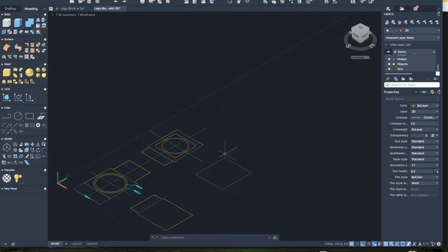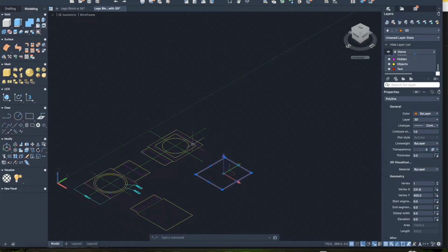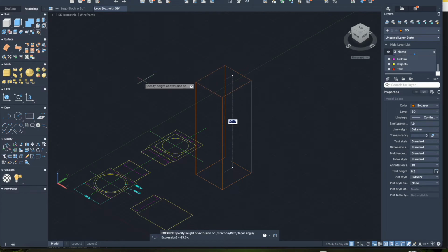Okay, we're going to select our box, which is the base of the Lego block, and find Extrude. Yours is along the top. If you can't find it, just type in Extrude. That's the beauty of AutoCAD. You can just type everything in. If you look at the chart that's been handed out, you'll see that the height of this is 100.